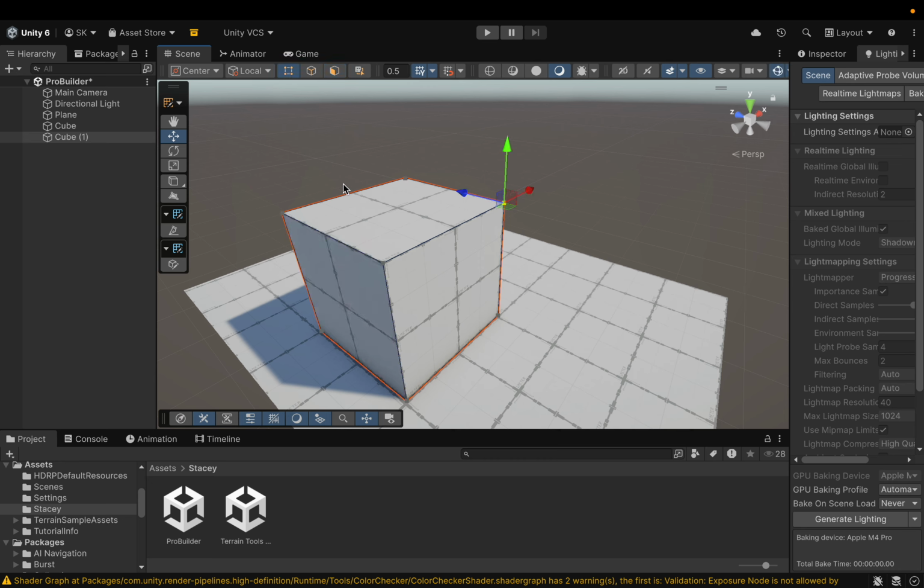And the points where they meet, of course, is the vertex. Then you've got edges where you can select your edges. On each of these tools, you can use your standard toolbar of move, rotate, scale. So let's say I have my edge tool selected here.